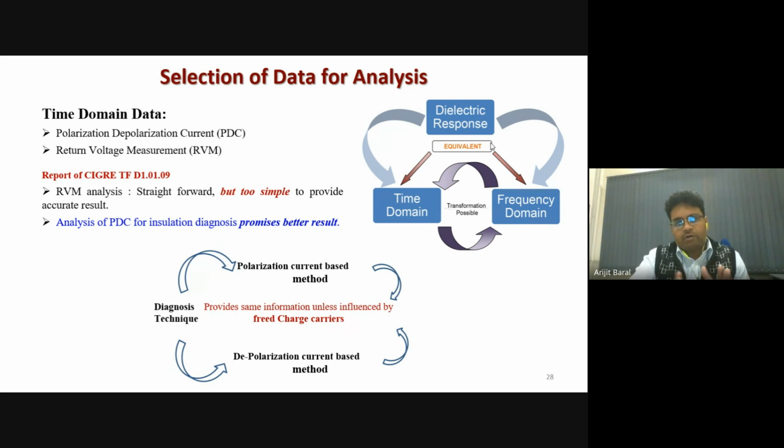If you're talking about oil paper insulation, in an abstract sense, it is nothing but paper immersed in oil. So this basically behaves like a dielectric material. Think of a parallel plate capacitor, and within this parallel plate, I have inserted an oil impregnated paper, which is how you get paper capacitors. Then if we apply a DC voltage across it, essentially it will behave like a dielectric material. So the response that you are going to get will be a monotonically decreasing current.